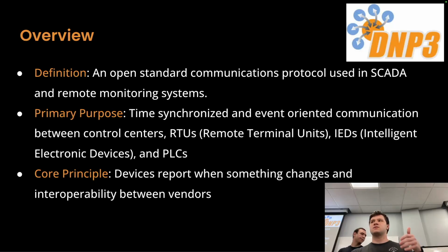The main core principle is that the devices report when something changes. With Modbus, your slaves can't actually send data back to the masters. With DNP3, the whole point is to have your sensors and things like your IEDs send data back to your master stations.